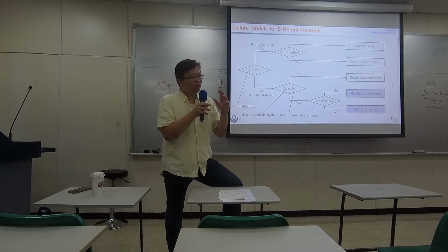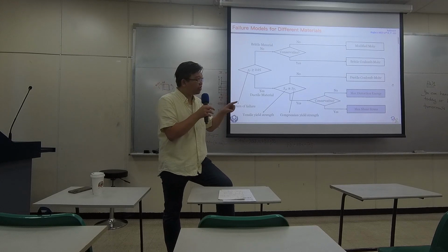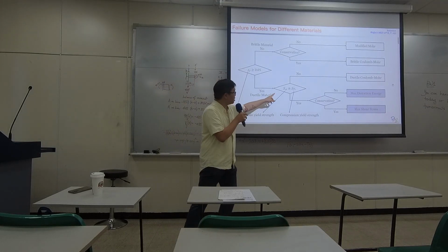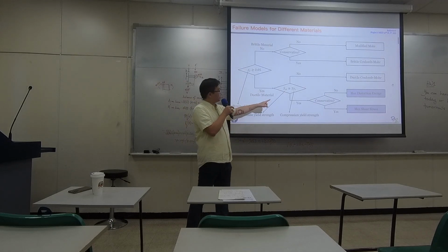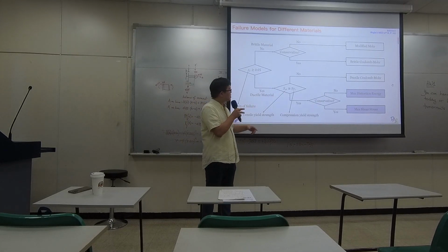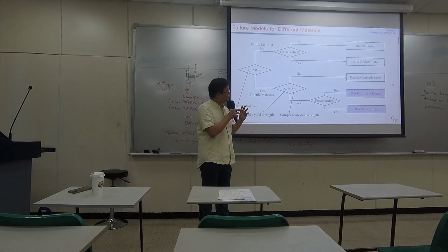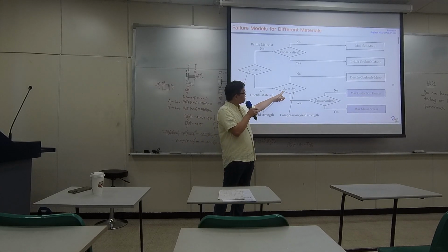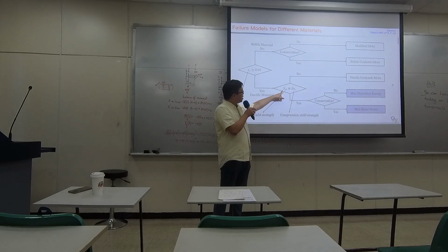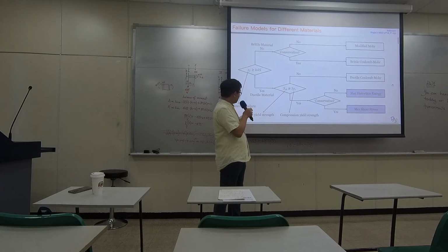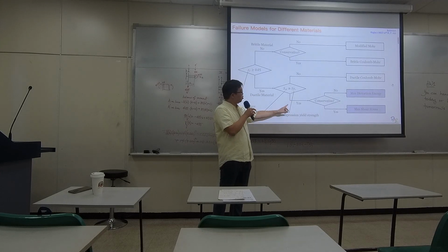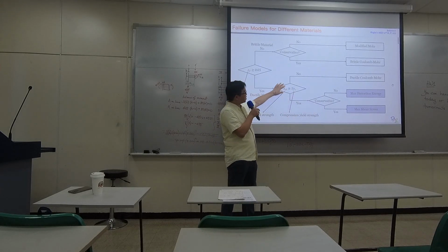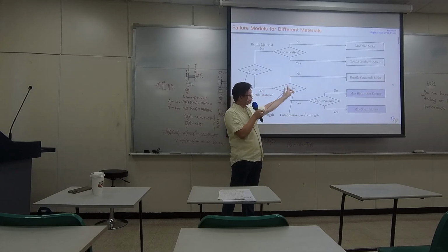And when it's about to yield, the principal stress that is about to yield is defined as the yielding strength. So there's a kind of material that mostly has a very close yielding strength on tensile and compression. When they are very close, it goes to the bottom. There's the other kind, it goes to the top.